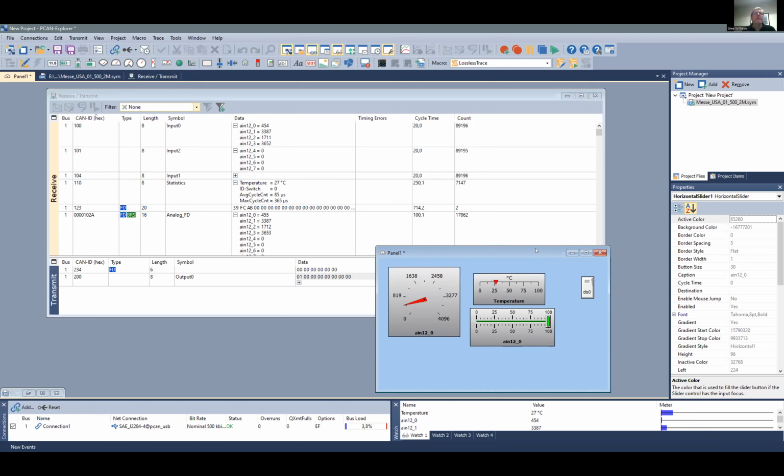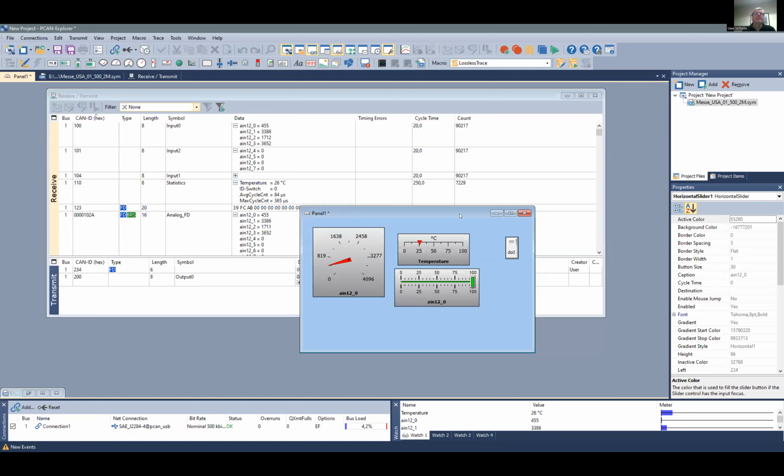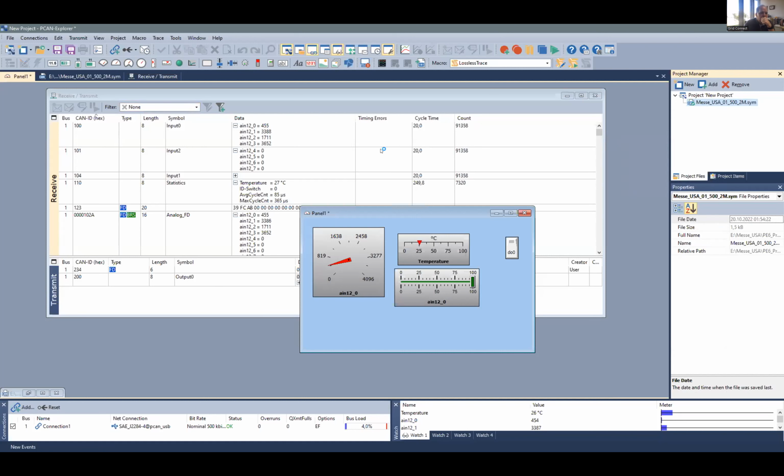What is possible is if you have, for example, a symbol file which has a CAN ID 100, and then you have 8 data bytes. And the value of the first data byte, if it's 0, then the next data bytes have their own signal values, like a multiplexer. I can show it. Also, simple multiplexers are possible. Then you use the first data byte also as information. It's like an extending of the CAN ID of the symbol. Now, if it's clear, maybe I can open the symbol editor.